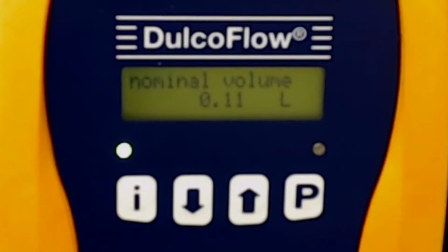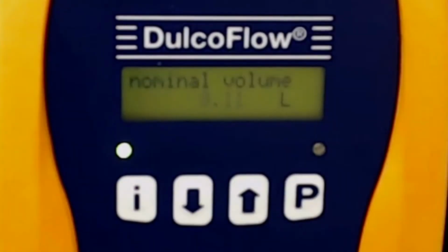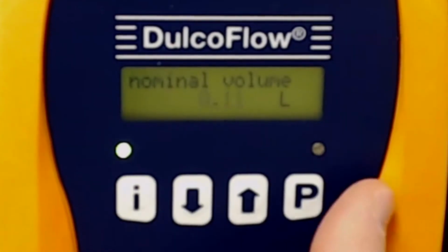So typically on that calibration column, we have to draw down in milliliters, and then we convert it to either gallons. So we would have to divide the milliliters by 3785. There's 3,785 milliliters in a gallon. Or we would divide it by 1,000. There's 1,000 milliliters in a liter to get to the liter setting.